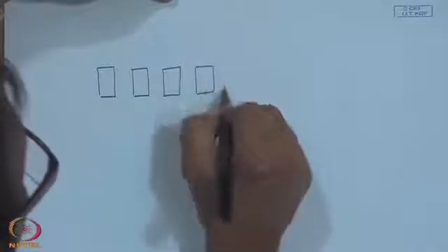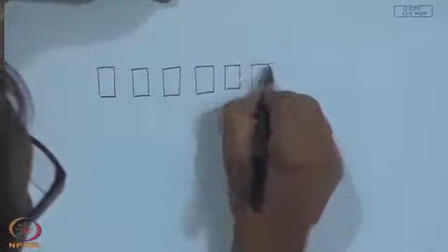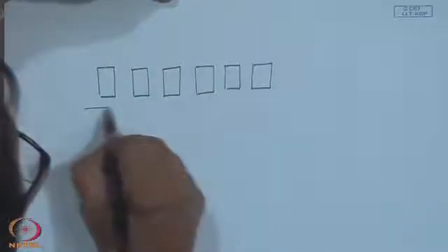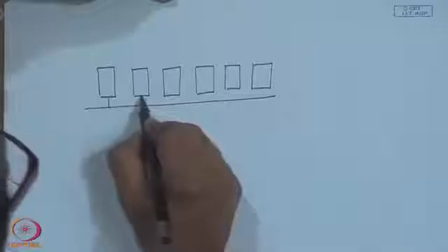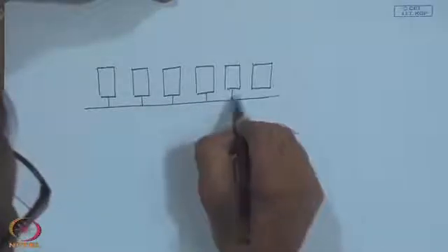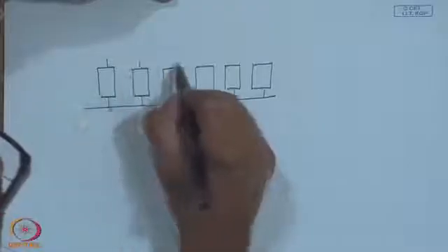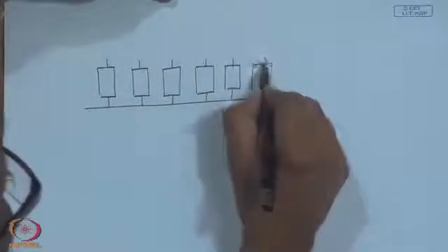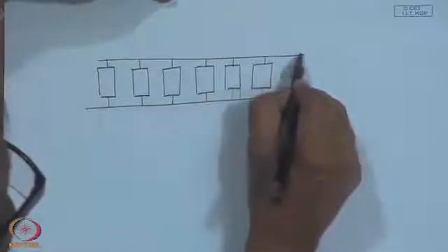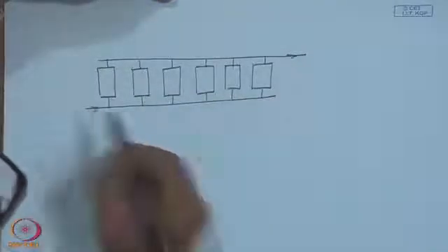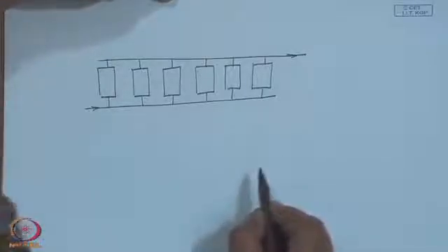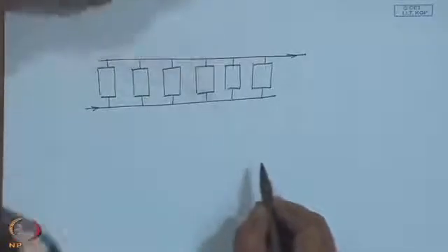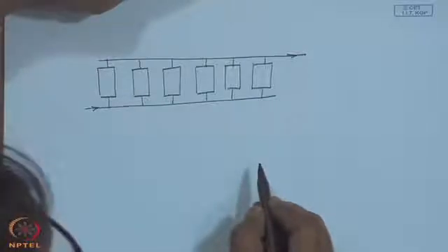One way is, I will take it for the time being, just 6 collectors. So, let us say there is a large header connected to this, connected to this, connected to this, and all the 6. Then again the delivered hot water will come out through these 6 collectors, and I have some sort of a pressure balancing, so that the flow through each collector is uniform in addition to the headers and risers that we discussed providing uniform flow in the collector.